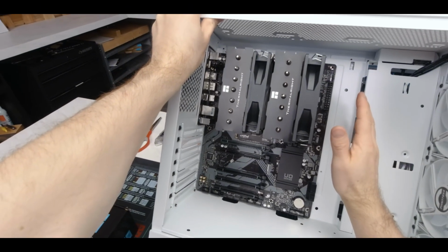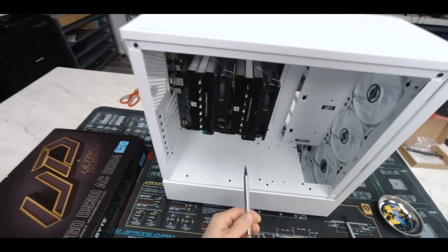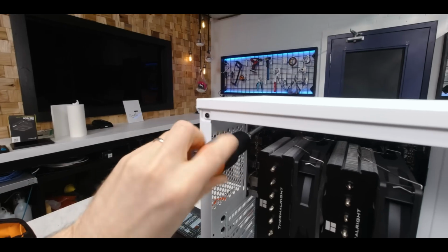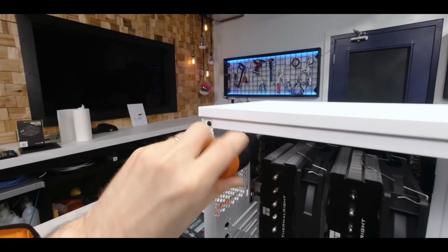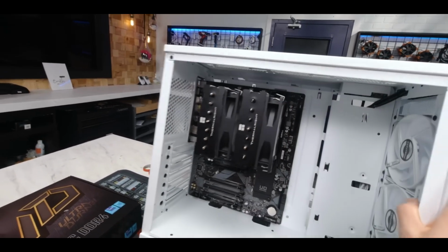And then line up all of the screw holes of the PC with the motherboard screw holes and screw them all in. Sometimes the motherboard will have extra holes or the PC will have extra screws. If they don't fit with the motherboard, do not try to make them fit. You only need however many are provided to you.